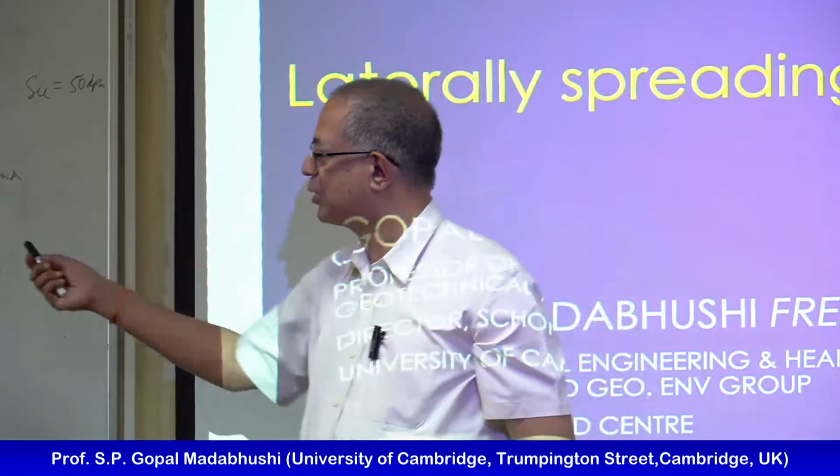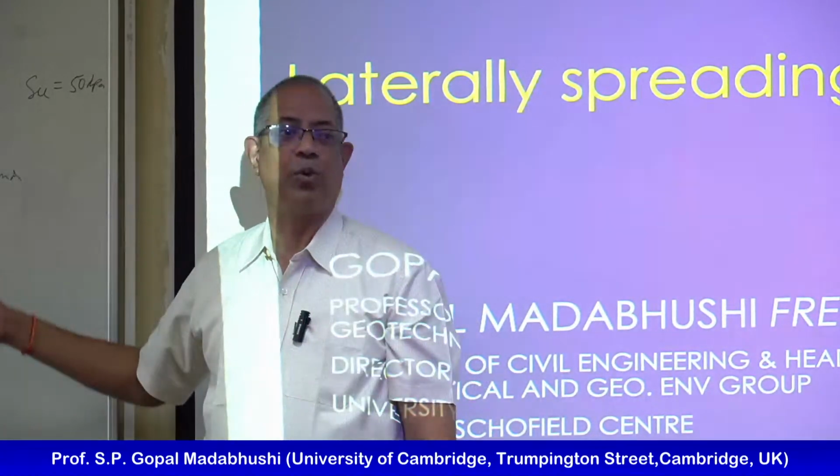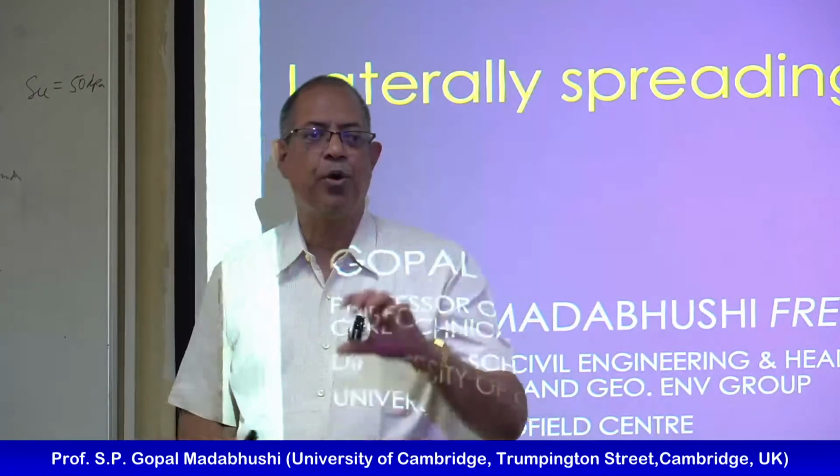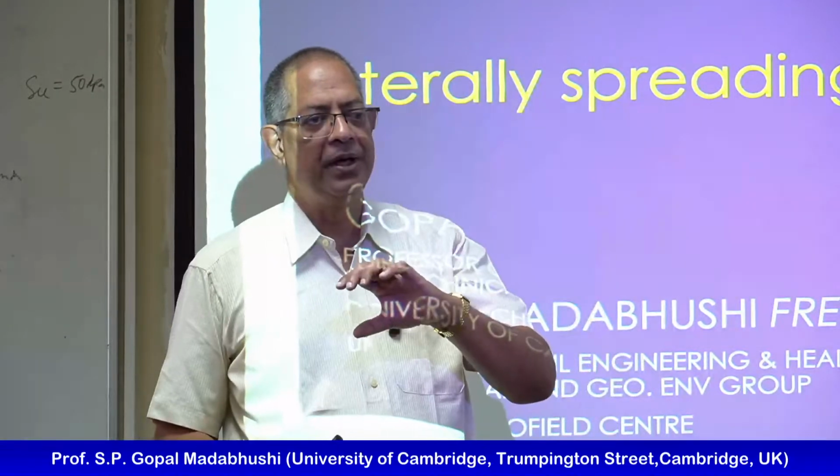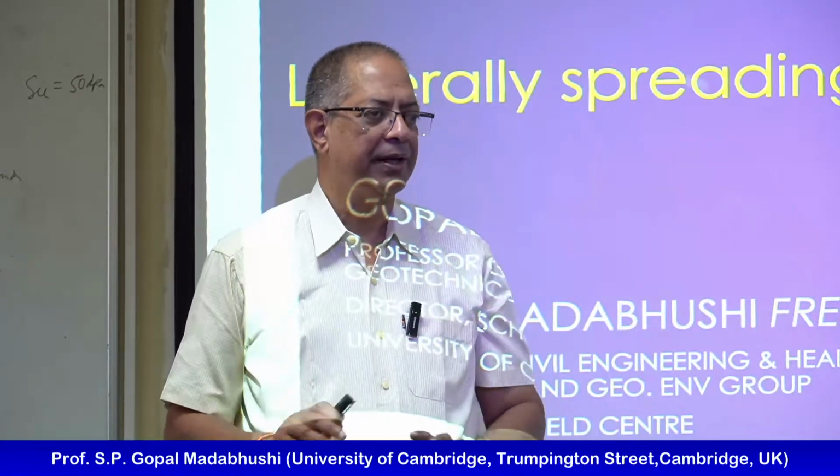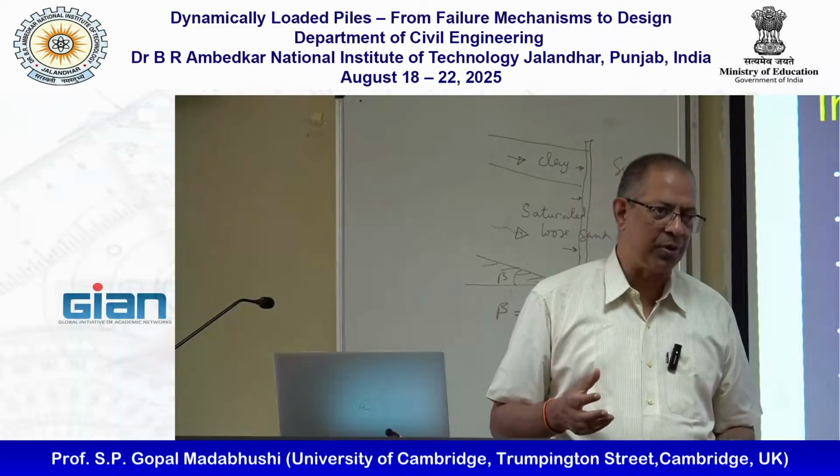So liquefiable soil applying load is one thing, but if you have non-liquefiable crust on the top, that was an even bigger problem for pile foundations. Does that make sense? So those are the kinds of earthquake related problems.